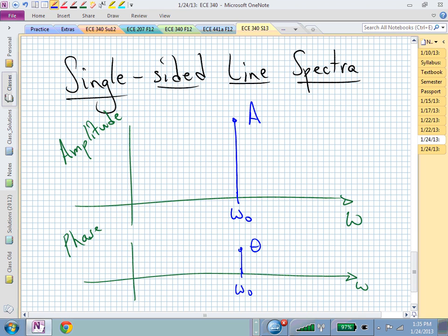Now, if you had several different sinusoids, they would each have their own spectral line. And now you can start thinking about, oh, what if I didn't want that frequency, but I wanted these frequencies? How would I filter that? You now have a picture of what you might want to do. These are the signals, and now the system, via its Bode plot, tells you how it's going to shape these signals as these signals are processed through that system.